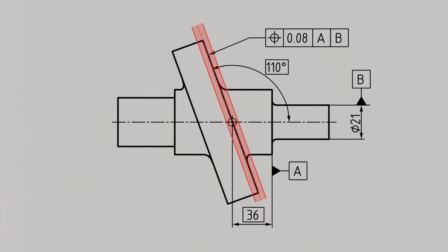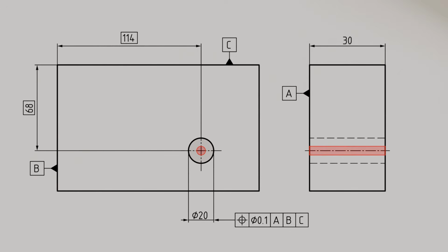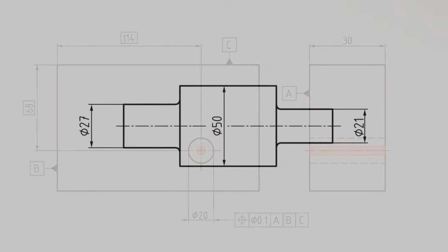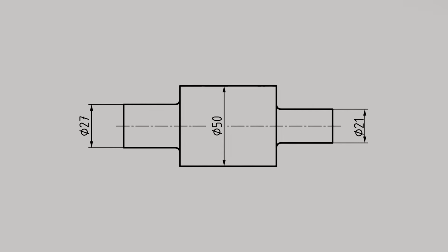Similarly, in the previous example, the straightness of the tolerated centerline is directly determined by the position tolerance. Since the centerline must lie within a tolerance cylinder, its straightness must not deviate more than the tolerance value of the position. Let us now take a closer look at the tolerancing of coaxiality and the special case of concentricity. Coaxiality or concentricity may only be applied to derived geometry elements, that is, in particular to centerlines or center points.